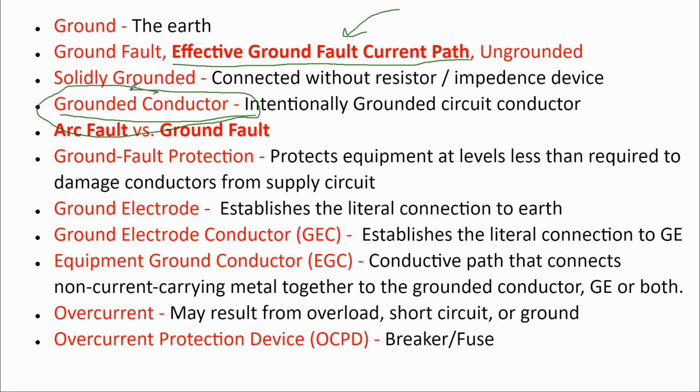So the return path for electrical flow in AC wiring is the neutral. And the neutral wiring is intentionally connected to ground in order to create that voltage differential so the electrons can flow from the hot legs to ground.